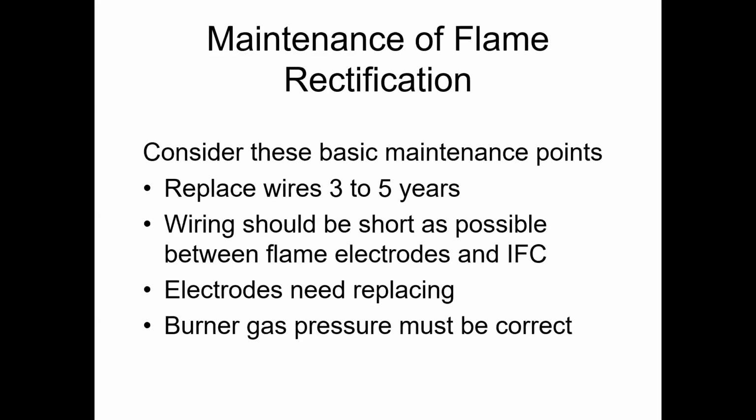Maintenance, you can replace the wires. It's saying every 3 to 5 years. If it's really an issue, if it's a common problem with the system, I'd say yes. But typically, if you're replacing wiring, it's not like it comes in a bundle. You're having to cut, strip, and crimp on connections for everything. So it's not a quick and easy repair, but it is a good thing to maintain: replace wiring once in a while, especially if it looks worn.